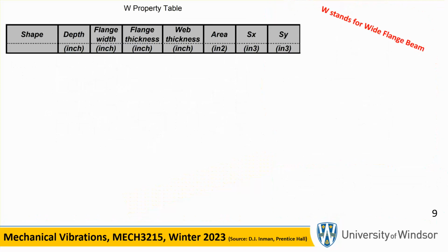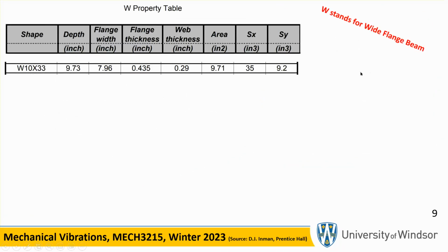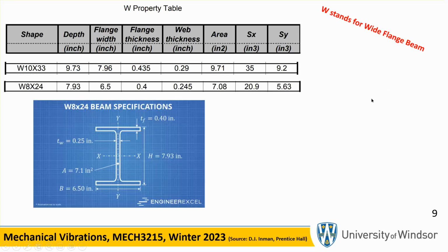Now, very often mechanical engineers don't do this, but it's kind of unfortunate. First of all, the W in that designation W10x33, W stands for wide flange, okay? And there are tables like this. I'm sure you saw it in Hibbeler's book too, when you took stress analysis perhaps, or your deformable bodies class. In the back there are tables of the different types of wide flange beams. So you see tables like that. These are the designations for the two beams that are being used here.